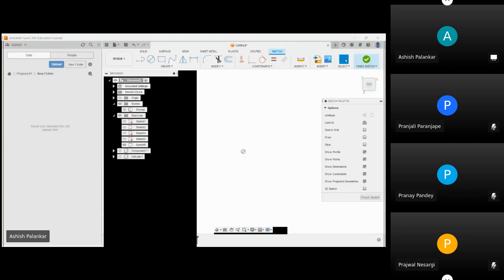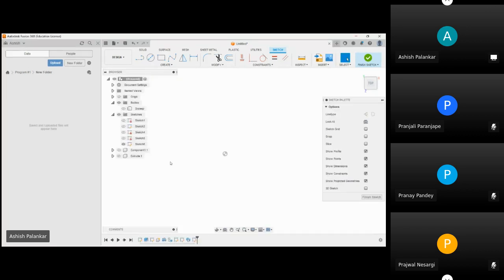Okay. How are extrude and sweep different? Don't they deal with the same thing but in a slightly different way? No, no. They both are different. I will explain it to you by using the tool. So the extrude part will just convert your 2D sketch into 3D. But the sweep is different. You can create a profile by giving a path. Like, you cannot create any pathed profile by using extrude.